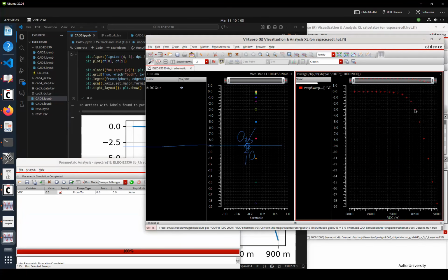Okay, then yeah, we identified it again. So at 0.82 volt, it experiences minus 3 dB compression, or minus 3 dB attenuation. Your goal for CAD exercise 7 is verifying improvement over this range. For example, if you run the bootstrapped sampling switch, it will be like this.